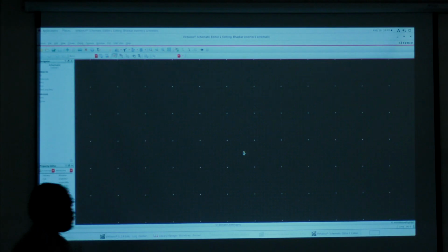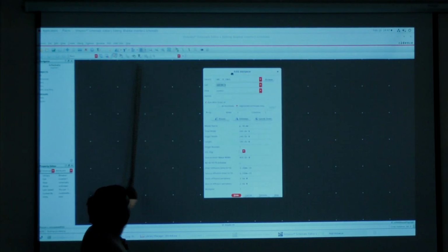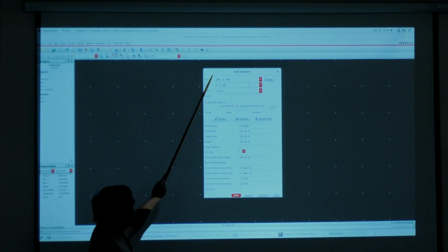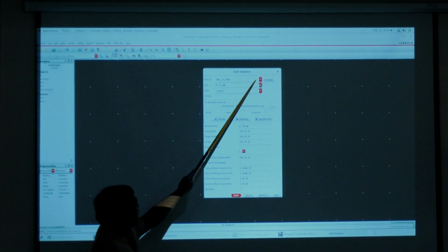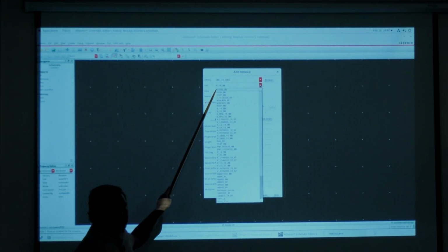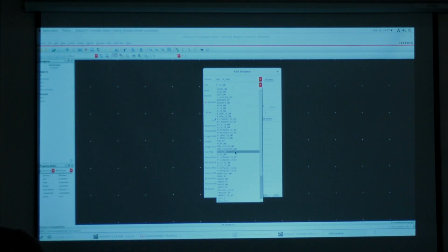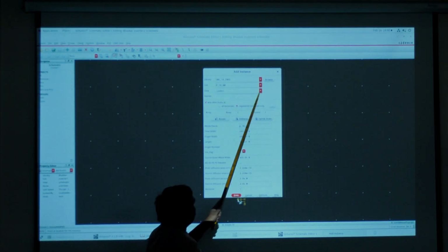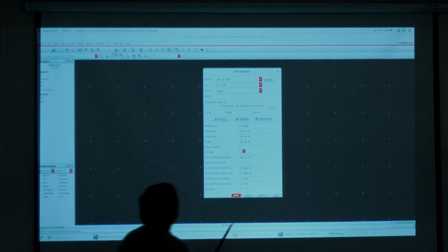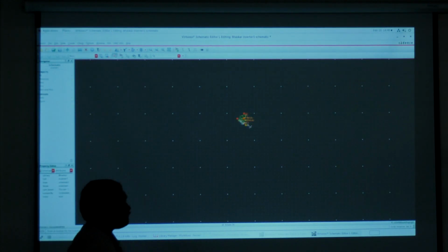Here you need to call the instance. There is an option, Instance. There you need to select the library name UMC. The technology we are using is UMC 180 nanometers, so it is UMC 18 CMOS technology. Select the library and the cell view. The cell is P_18_mm. You need to take P18. Don't go for P33. Take P18, view symbol, and next hide. You get a P type.